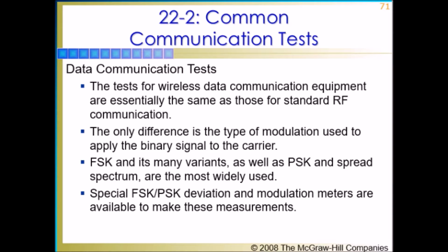For data communication applications in which binary signals are baseband on coaxial and twisted pair cables, such as in LANs, more conventional testing methods may be used. For example, a binary test pattern may be initiated in the transmitting equipment and the signal viewed on an oscilloscope at the receiving end. Tests of the signal attenuation and wave shape can be made.